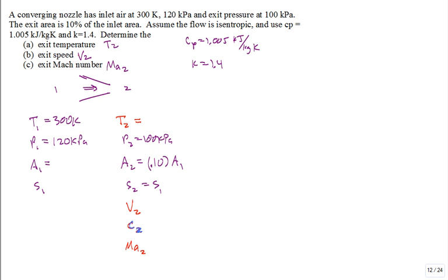We have a control volume, so you do the entropy balance, or you just exploit the final result about how temperature and pressure change for an isentropic process in an ideal gas, which is the equation T2 over T1 is equal to P2 over P1 to the K minus 1 over K. True? That's what you do.